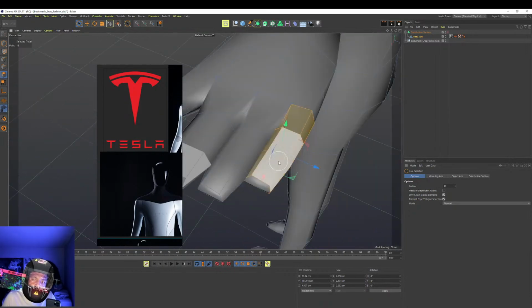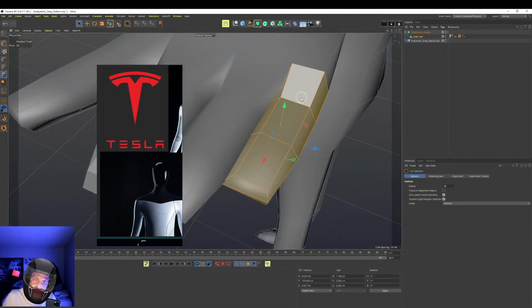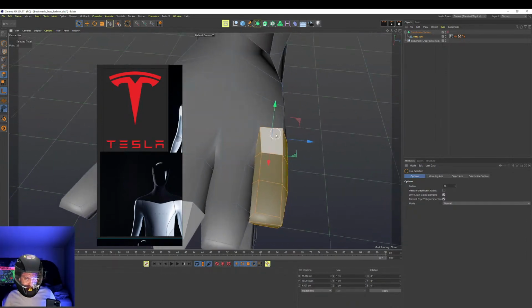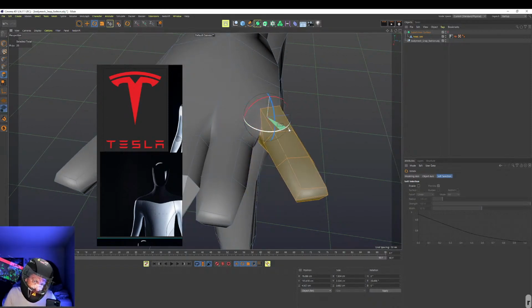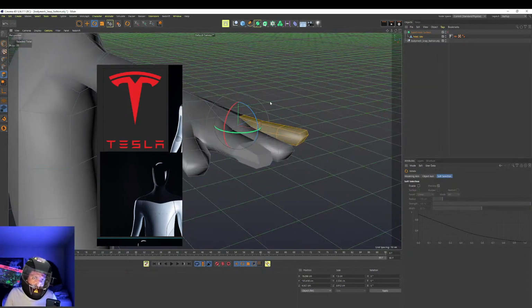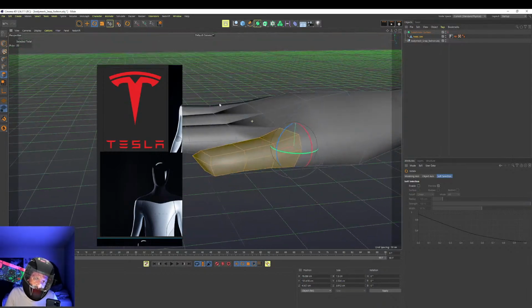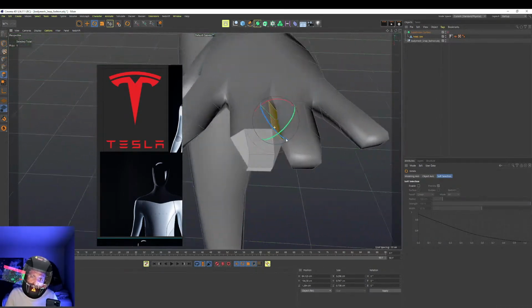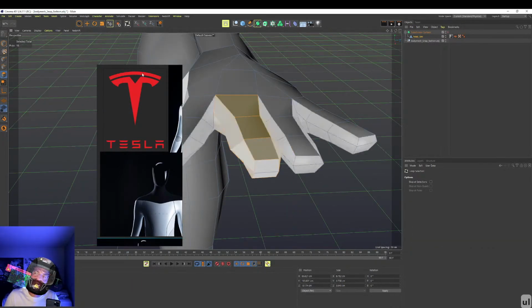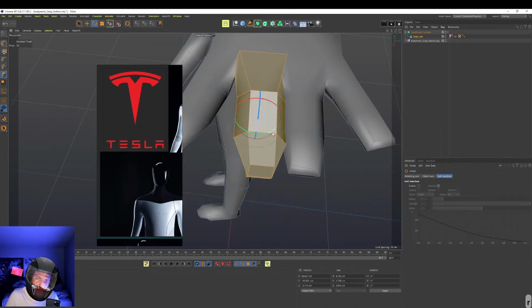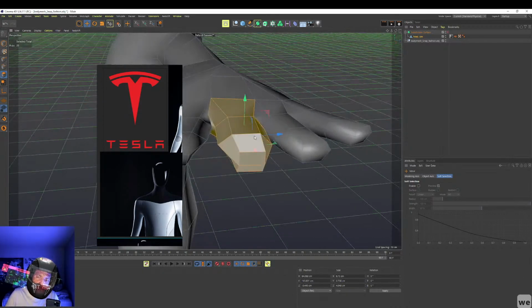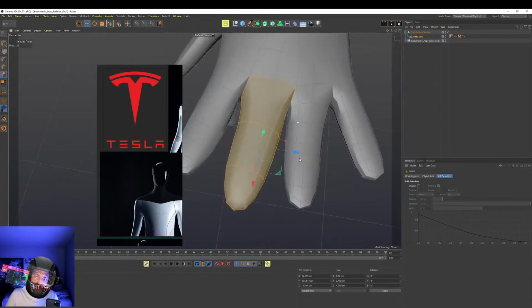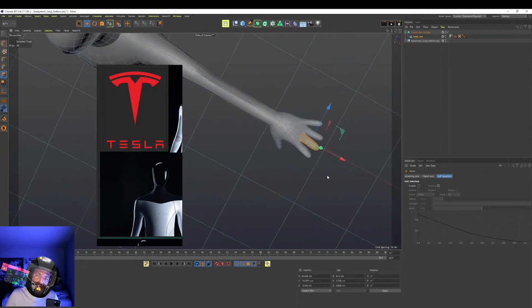So what I'm doing right now is called polygon modeling. Each of these little squares that you see highlighted, these are called polygons. And every 3D model, for the most part, is made out of polygons. And what's cool is you can use polygons to define really any attribute about a model. You can decide its shape, its texture, its contours, and a lot of the makeup of a 3D thing can be done through its polygons. And so what I'm doing right now is trying to space out the fingers so that when we bring it into a different tool, the fingers won't merge all together. They'll all stay separate, which will help a lot in the next phases. So I'm going to need to do that. It's called splaying. You want to do some splaying on the fingers.